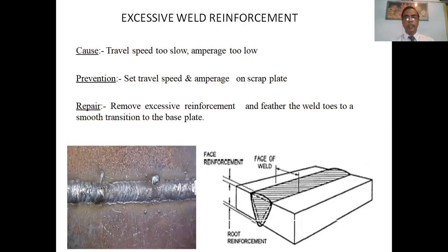Excessive weld reinforcement. This is excessive. It is welded more than needed, which means extra amperage was there, so it melted over.